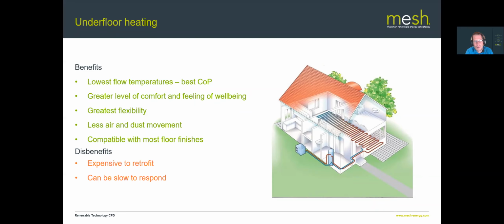And also, underfloor can be quite slow to respond to changes in room temperature, because you're dealing with quite a lot of thermal mass. Even when you tell the underfloor heating to switch off, it will take quite a while for that to cool down, and it will also take quite a while to heat up. Now, that in and of itself is not a problem, because what you can do is set the control system to respond to that.